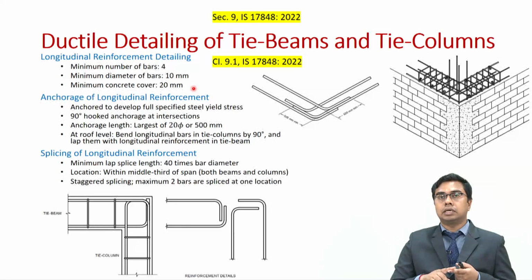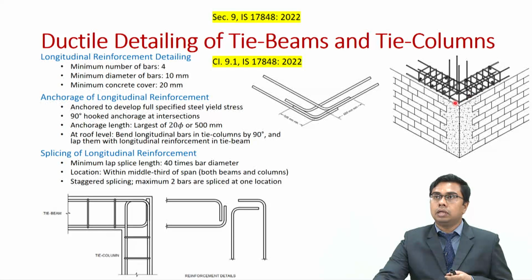But when you are constructing a reinforced concrete frame building, the frame is the load bearing system, and therefore you cannot expect a deterioration in strength or poor durability in a reinforced concrete frame. But in confined masonry construction, since the load carrying system comprises walls as well as these confining elements, you can afford to have some deterioration with time or some loss in durability.